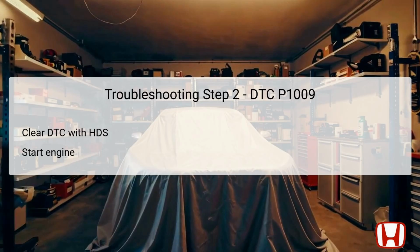This step establishes a baseline before further diagnostics take place. Once the engine is started, the next step is to check for any pending or confirmed DTCs using the HDS. This diagnostic tool will list any current codes that may have triggered during the engine's operation. If DTC P1009 is indicated again, it confirms that the issue persists and needs addressing.